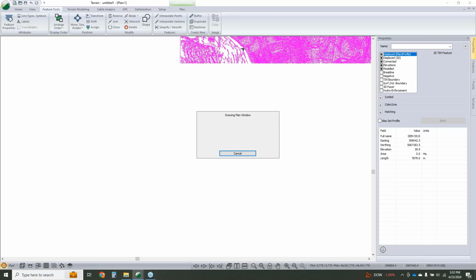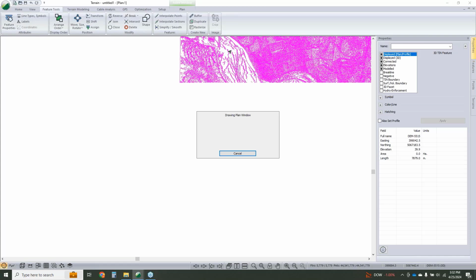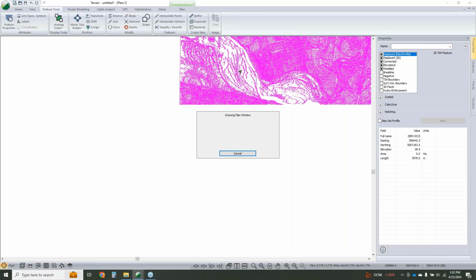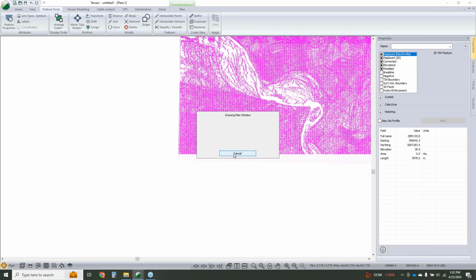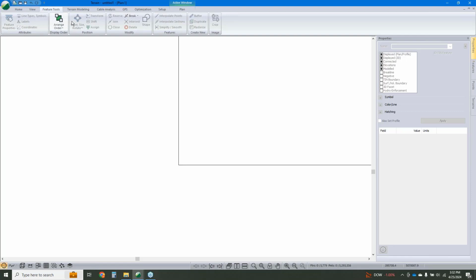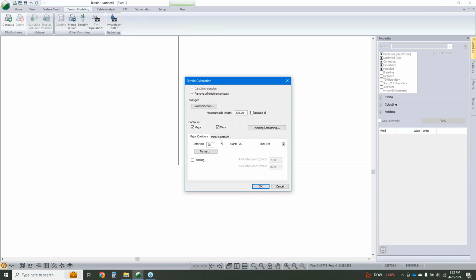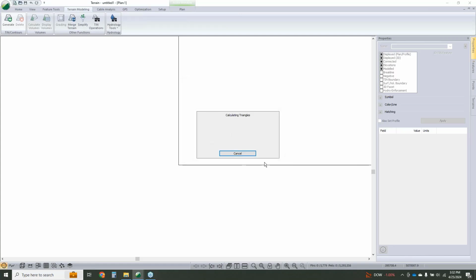And as it's drawing here, we can see we don't have this solid wall of gridded points. We've got all the, well, the redundant points removed on those really planar slopes. We're going to model this. So we're going to go up here again, click Generate Model. I'm not going to create contours, they're just going to add clutter, make it harder to see what I'm going to show here in a moment. So we're down to 5.2 million points. So 44 million to 5.2 million.